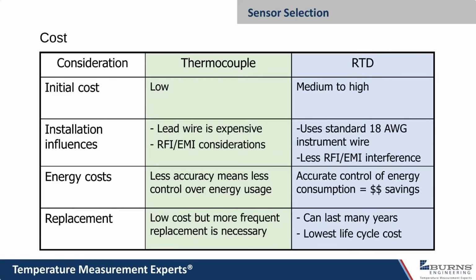energy costs. This is where I get back to always start with an RTD. Because if you're heating or cooling a process, you're going to have much better control over that, and much better control over the money that it takes to heat or cool that process, if you have an RTD that's been installed correctly and gives you a good, accurate, repeatable, long-term measurement.